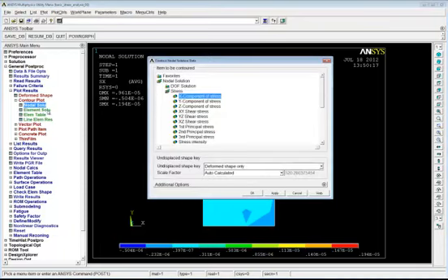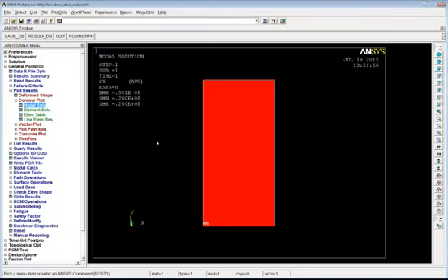Let's just go back and look at the Y component of stress. What's happening? That was 0.1 the last time, and we determined that was correct. Why is that 0.2? Unfortunately, we put the force on the symmetry boundary condition. So basically, that force was applied twice, because what Ansys does when you put in a symmetry boundary condition here is it mirrors everything over into the other side. Okay, so it's also mirrored the load because that was there. So the load has been mirrored as well. So it's just something to be very, very careful. So in this case, we can reduce the load by 2. And again, we'll talk about doing that in subsequent analysis.